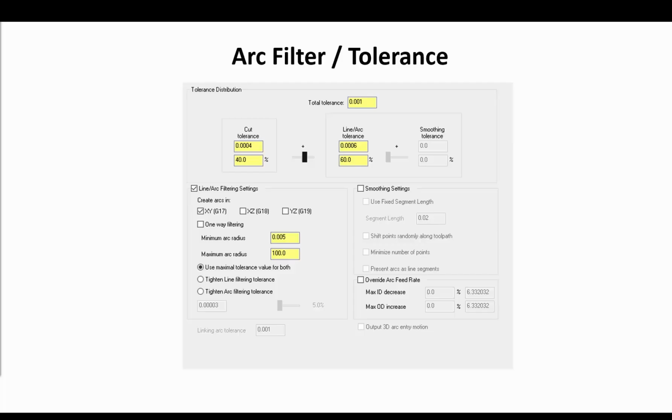The slider and data entry fields are linked. When you modify one, the other updates automatically. Smoothing improves the quality of the machine surfaces and also creates better cutting conditions for the tools, decreasing tool wear. This feature is going to be covered in Mill 3D.